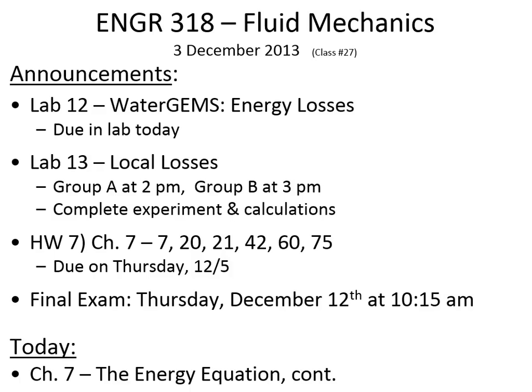Maybe less if you're fast at doing calculations. The calculations really aren't that complex. I've already handed out the description of today's lab, and you can see that what we're going to be doing is looking at some of the fittings. We're just going to do a single flow rate, and so you'll be able to gather the measurements relatively quickly, but the purpose of the lab will be to compute the K value for each of these different fittings and then compare it to the typical K value that's provided on Table 1.